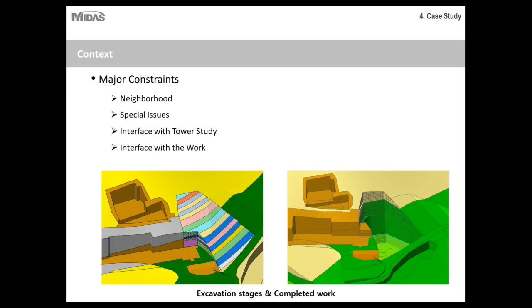The major constraint of this project site was that it was in a highly urbanized area. There were several adjacent structures, and the neighborhood was densely populated. There were schools and other community centers and active areas where the foundations were there, and they could not afford to disturb the foundations of the adjacent structures. So the excavation sequence must be carried out in a step-by-step process with layers of short height.